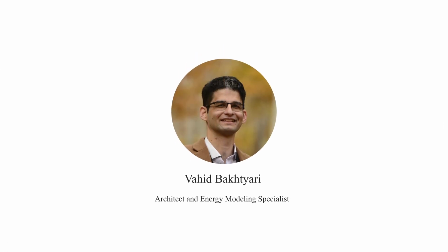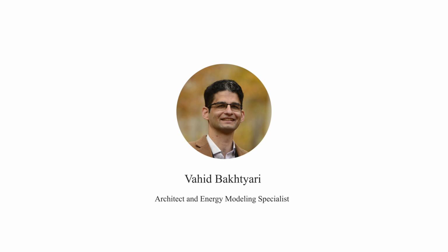Welcome to the hands-on part of our OpenStudio journey. In this video, we'll start modeling from scratch and build a complete, simple energy model step by step. We'll draw a 10 meters by 5 meters single-story building, add windows and a door, assign a thermal zone, space type, and construction set, and finally generate a full 3D model ready for simulation. By the end, you'll have a working OpenStudio model and the confidence to create your own. Let's begin.